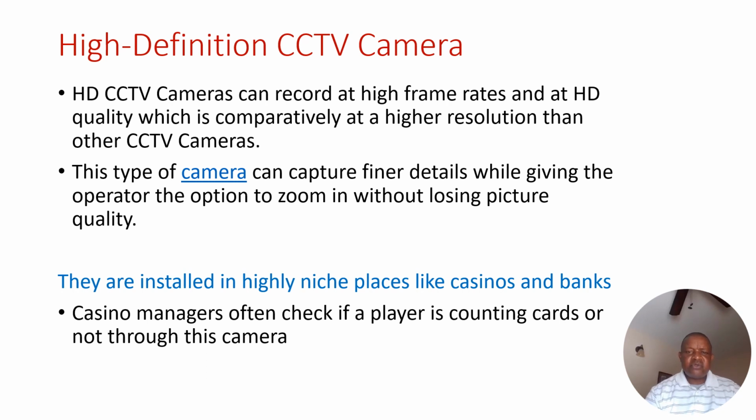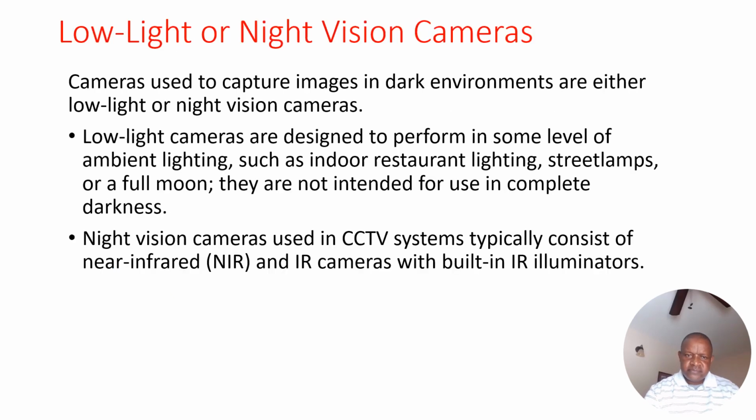Remember, I have been in a position of security management, and I've interviewed quite a number of CCTV surveillance officers, and this little information is what is lacking with the majority of CCTV controllers. They cannot tell between a bullet and a dome camera. They cannot tell if this camera is infrared or not infrared. They cannot tell if this camera is PTZ or what kind of PTZ. They cannot tell how a PTZ camera is operated, either manually or set automatically. Gentlemen, these finer details are very important to a CCTV surveillance officer.